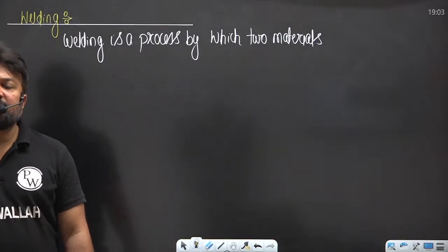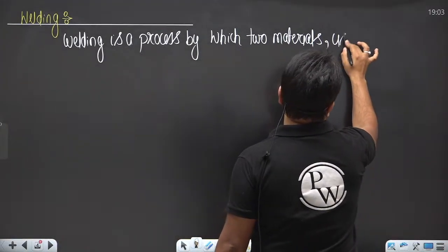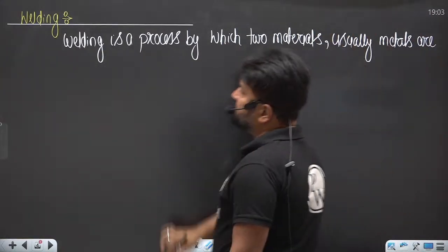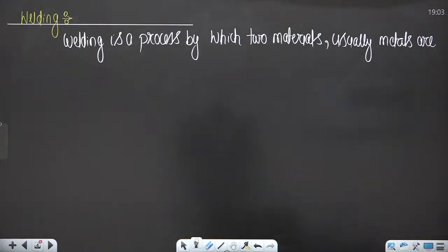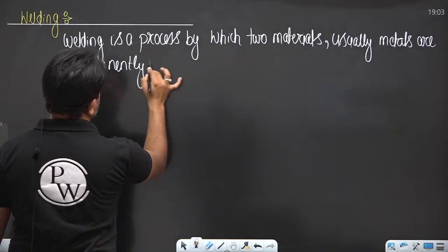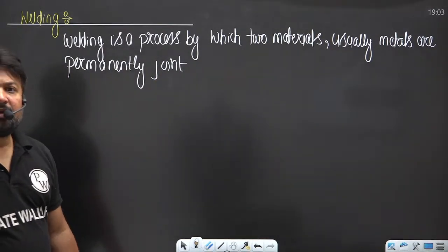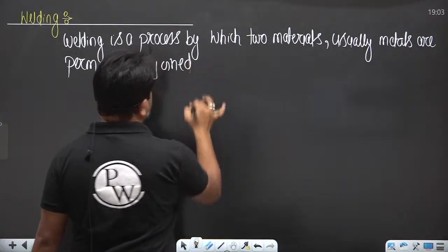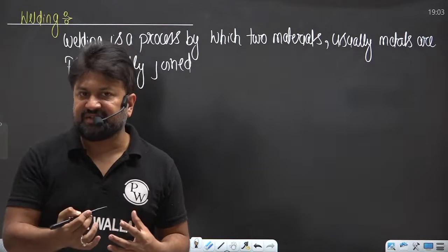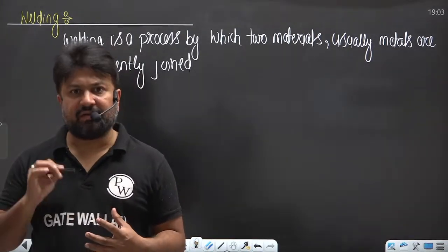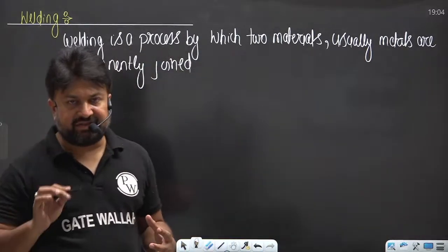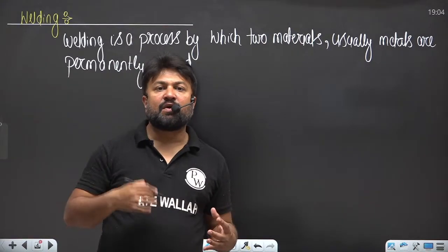two materials, usually metals, are permanently joined together by coalescence, which is induced by the combination of temperature, pressure and some metallurgical changes. The particular combination of these variables can range from a higher temperature with no pressure, to a high pressure with no increase in temperature.